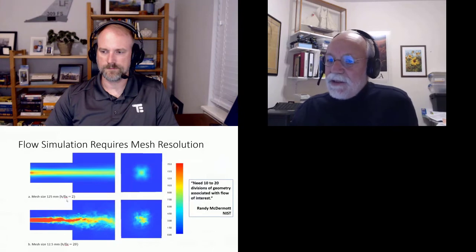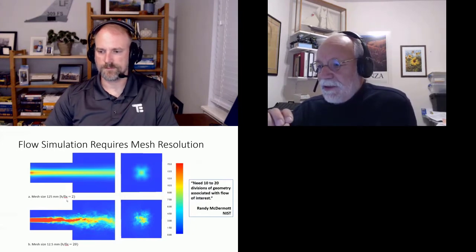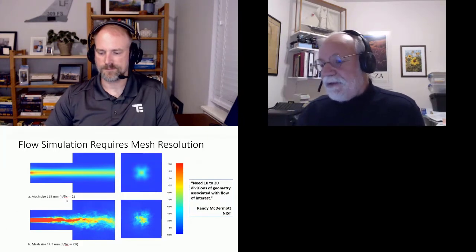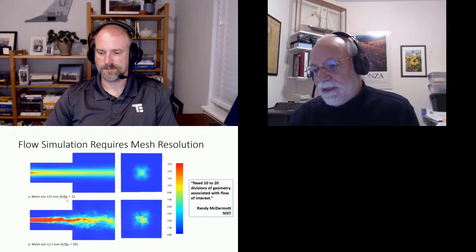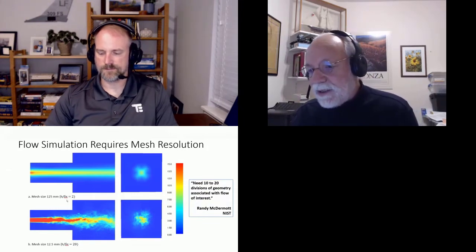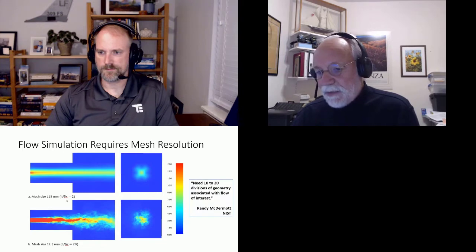So the challenge becomes, how do we actually do this with a good mesh resolution? We start with, I just used a duct and I used HVAC, and if you divide the exit into a 2x2 grid, so you have 4 cells at the exit, you just do not have the resolution that captures that transfer of momentum to the ambient air.